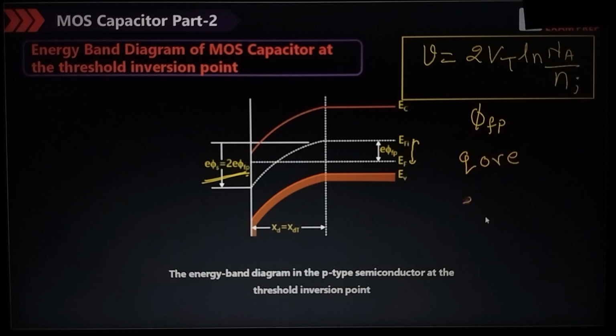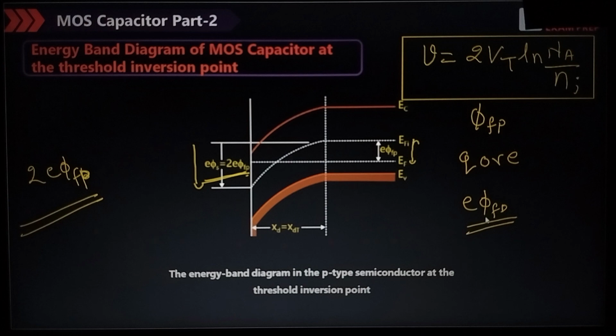This is the P type, and the depletion layer increases inside the P type. What was the formula? At junction potential Vj, it is given by Qn upon 2 epsilon s into W square. This was the formula, everyone. Here it increases on the P side, and that's why in place of N we are using Na.